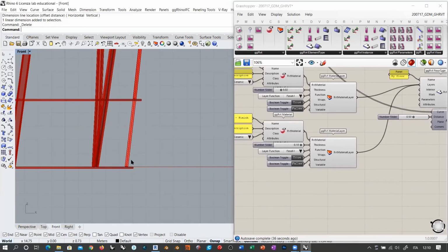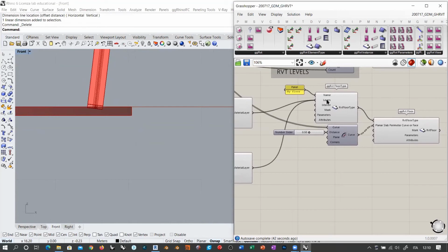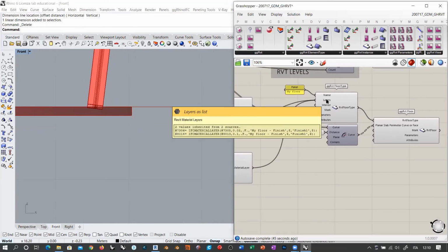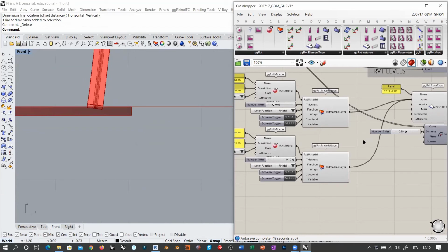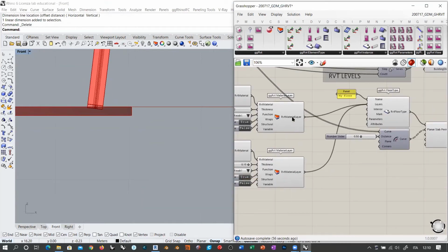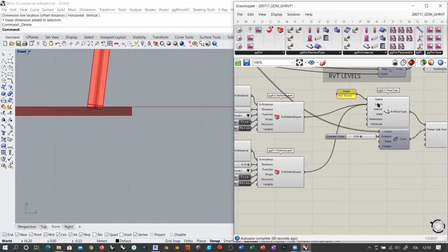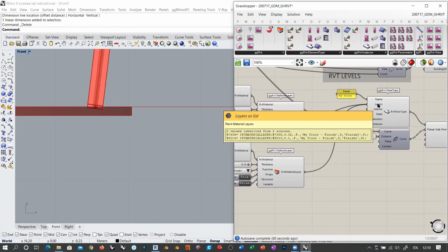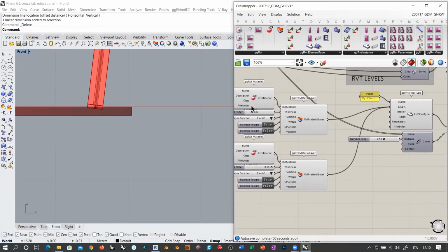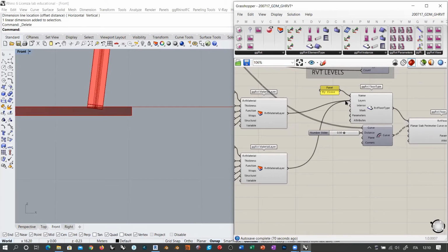And now just take a look at this. Always consider that for some reason, especially when you try to add several thicknesses or several things here, the output could be in a data structure that is not capable of merging when you plug this into layers. So always double check that in this case, layers is asking for layers as list. So you must provide a list. If you do something before the material layer definition, you might have some non-mergeable flows here.